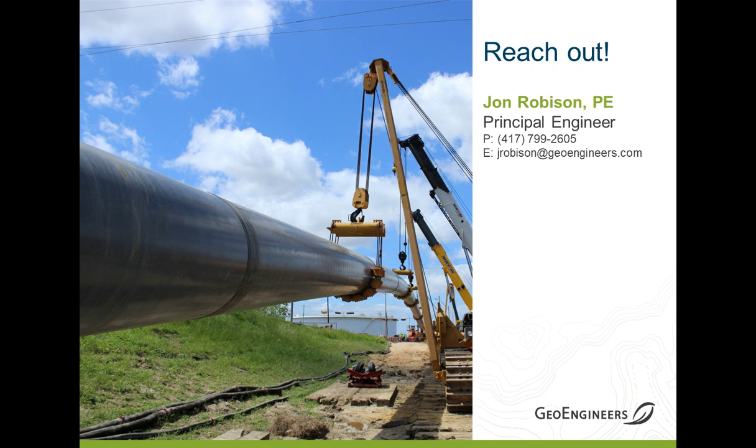On a long crossing, if you've got curvature at the start, you're going to have high axial loads, high bending stresses right at the start, and the numbers may not work out for you. So I think starting at 100D as a rule of thumb is a reasonable place to start.